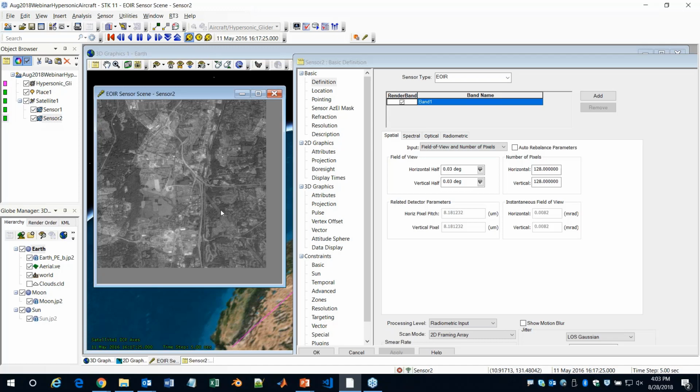Oh, so the SNR dropped with the longer range, and the idea is that even though the radiance would remain constant, the projected irradiance falls off with the distance squared. So, for example, when we're dealing with sub-pixel targets, normally you'd analytically solve for those with the intensity of your source, and the irradiance on your focal plane is going to fall off as the intensity divided by the distance squared.